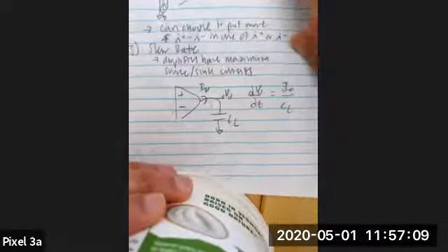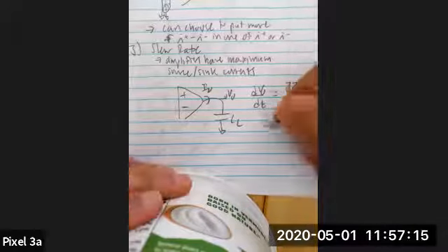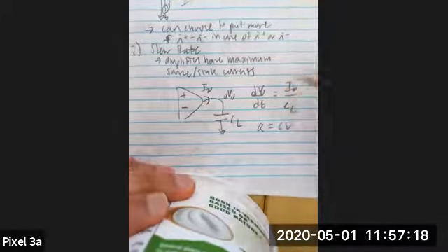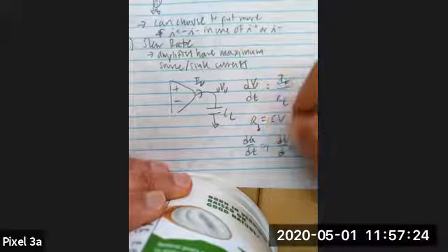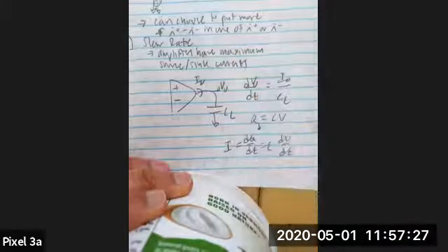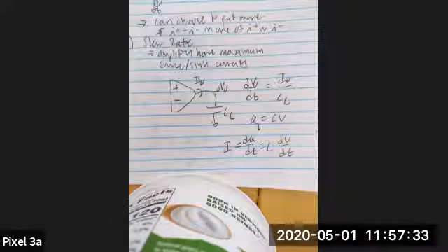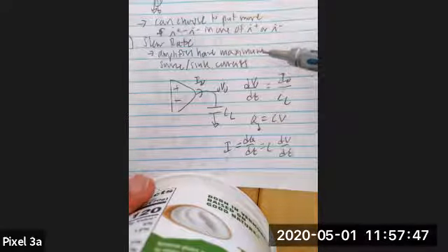And that just comes from capacitor dynamics. If we start with the equation Q equals CV and then differentiate both sides, we get dQ/dt equals C times dV/dt, and dQ/dt is nothing except the current. So that's a fundamental limitation of capacitors. This arises in our circuits because the amplifiers, as we design them, can only give a maximum amount of current based on the topologies and the transistors that we use. So this places a limit on the maximum slope of our output characteristic.